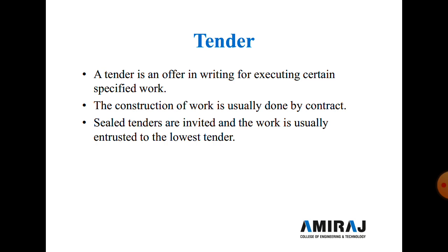So the construction of work is usually done by contract. Sealed tenders are invited and work is usually entrusted to the lowest tenderer. While inviting the tender, the bill of quantity, detailed specification, conditions of contract and plans and drawings are supplied to the contractors who wish to quote the tender rate, on the payment of the requisite tender cost.